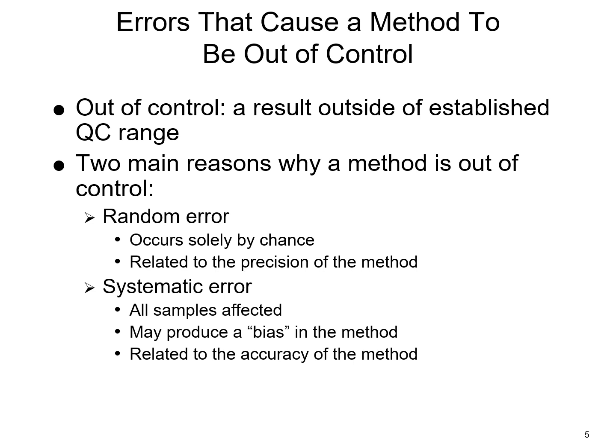So some of the things that you might need to do might be something like calibration or routine maintenance. Let's just say that you've got probes on your analyzer that need to be changed every so many months. Maybe somebody forgot to document that they did it, or they didn't do it, or maybe it's just being used a little bit more, so it's gumming up a little bit quicker. So it needs to be changed. Maybe you need to recalibrate. You know, there are a variety of things that can cause it.